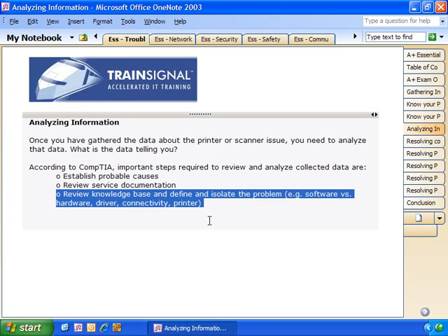All these things we went through, and finally it was determined that the cause of the jams was that the company that we got our forms from, the roll that the forms were being taken from had gotten very small, and what the effect was the forms had a bend to them. The forms were kind of arched, and this arch, as the form went into the printer and went through the different rollers and stuff, at one point the arch in the paper was causing the form to jam right there.